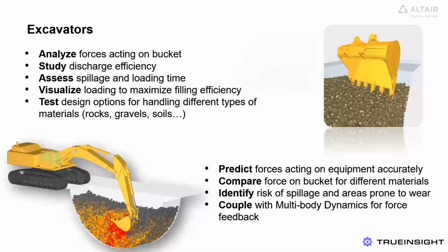Another common application for EDEM includes excavators. An excavator digging through a pile of rocks will require a stronger bucket and much more power than for a pile of dry sand. And designers also have to then account for different deformations on the bucket arm due to the loading. The level of wear on the bucket may also vary based on whether a material is abrasive, like sandstone, or less abrasive, like a soft soil.